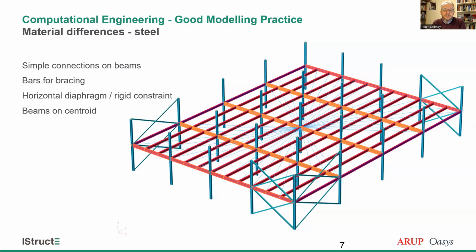It can make a slight difference once you get to the columns at ground floor level. Just something to watch out for: just double check the lengths of the columns at ground floor when you go down to the foundations.